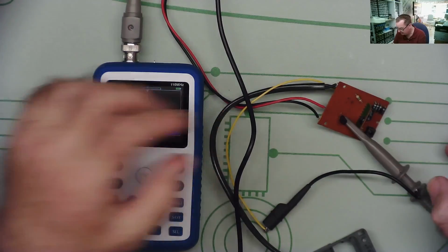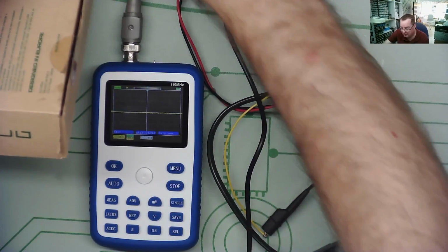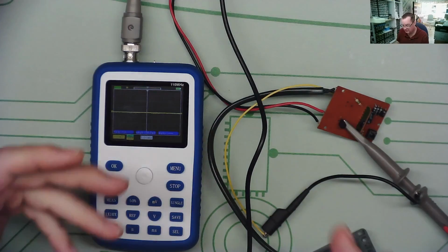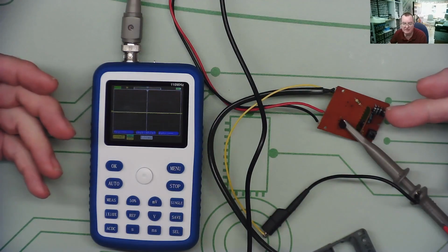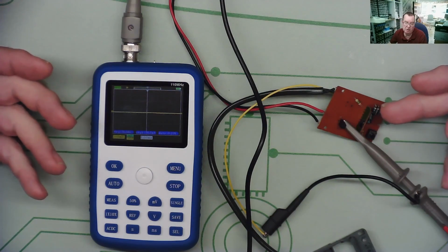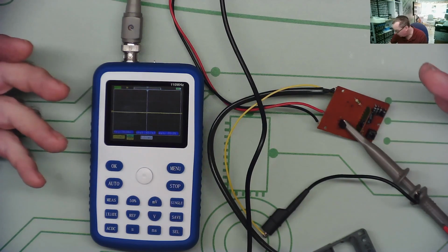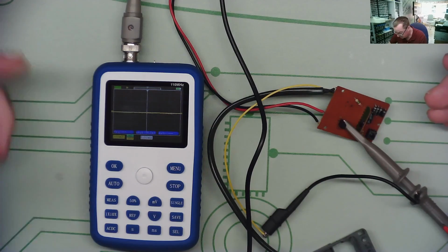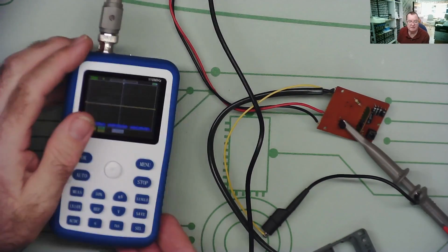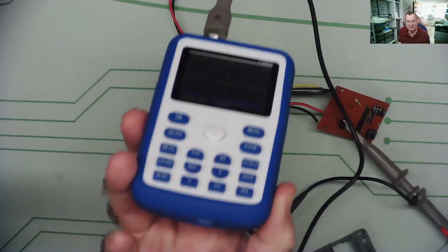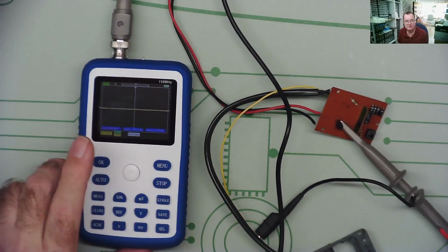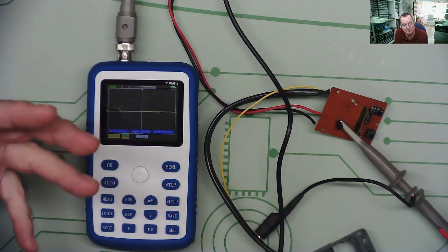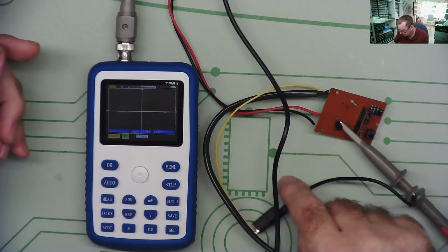I've now connected the little PCB to a light bulb. The light bulb is 65 watt. The rating for this thyristor was half amp continuous, which on the 220 volt is about 110 watts. So it's more than capable of driving the lamp. I've connected the handheld oscilloscope, so this is not connected to anything, it's completely isolated from the mains, and this is important, otherwise you can't do what I'm doing.